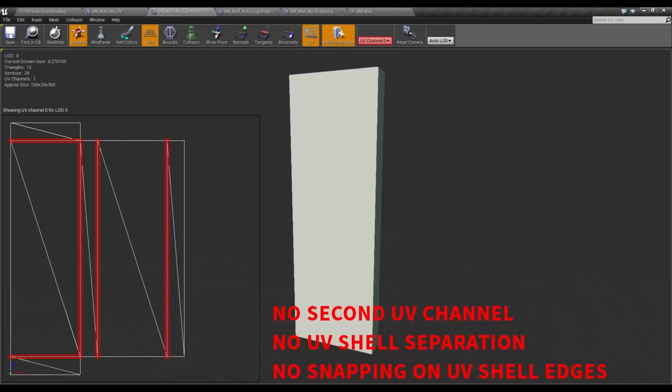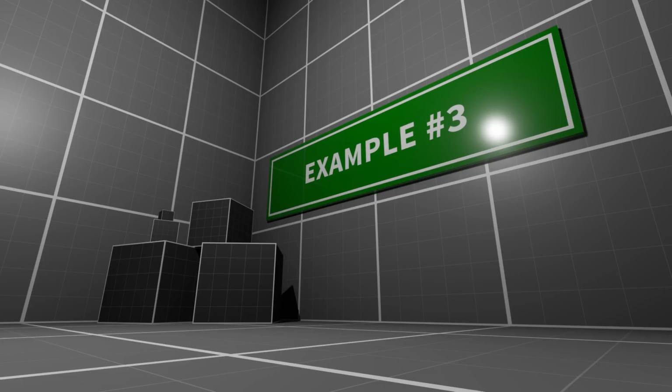So why is this a problem? Well, when creating a UV map specifically for a diffused texture, it's not uncommon to overlap UV coordinates for the sake of space efficiency, or to use a singular UV shell to achieve consistent scale and to minimize seams. However, both of these approaches are detrimental when creating a UV map for a lightmap, and will result in light and shadow bleeding.